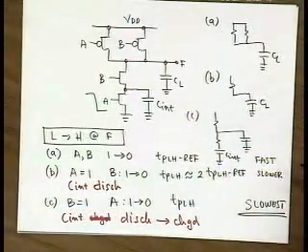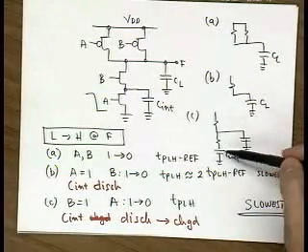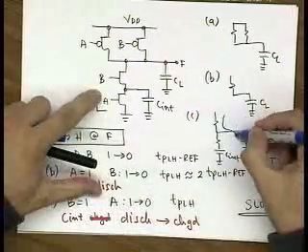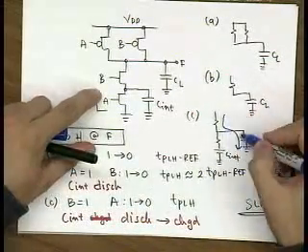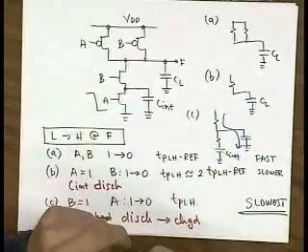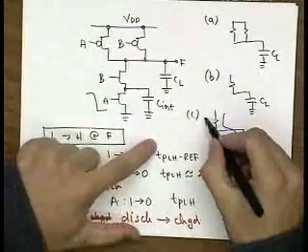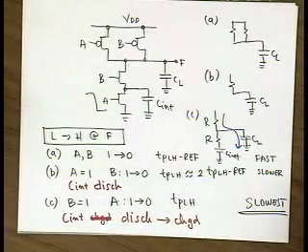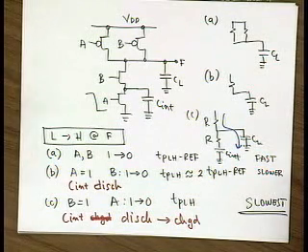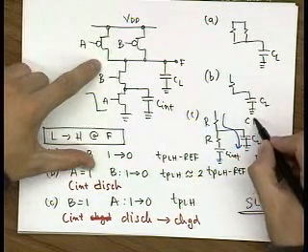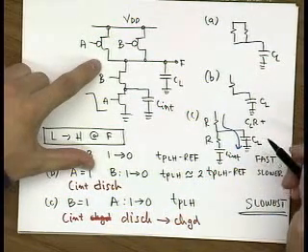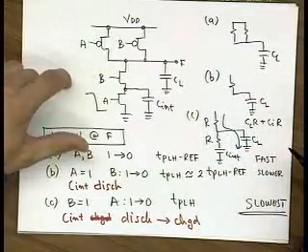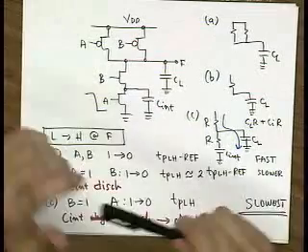Remember the Elmore delay formula? When you have a configuration like this, you have time constants from these off-path guys. That's the example we did a couple lectures ago. So this is basically your Elmore delay. What's going to be your Elmore delay here? Anybody? If this is your R, this is your R, and this is your CL, so CL times R plus C intrinsic, which is also times this common R, right? Okay. Good.